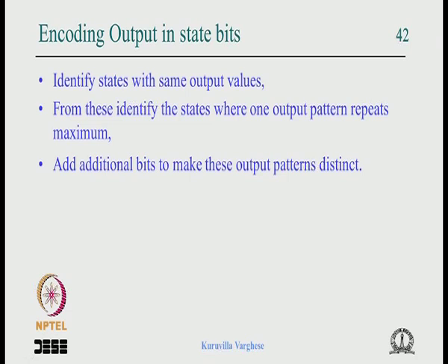Today we are going to look at a serious issue called synchronization, and that is related to an issue in a flip flop called metastability. Basically it is an issue inherent in a cross coupled latch. Since we build flip flops out of a cross coupled latch, the same problem comes in the flip flop, and we build the data path and the finite state machine using flip flops. So we again have the same problem.